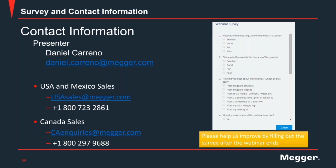The other thing that you want to make sure of is that the vector group is selected right. Selecting a wrong vector group would result in an obvious error, and the ratio errors that you would get would be much higher than 0.5%. But these are the two main factors you would want to look into to avoid operator error. Besides that, if you did the testing in the right manner and the value is still high, then there's something wrong with the transformer, and it needs to be investigated. It may be that the transformer is designed in that manner, but again, the standard says that 0.5% is the limit for transformers.